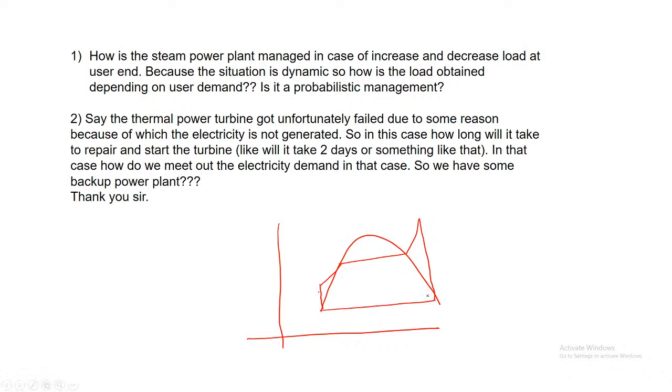This is our Rankine cycle in our TS diagram, and here we have 1, 2, 3 and then 4. Consider an ideal cycle with all efficiencies as 1. Now we are bleeding certain steam from here, which is 5. Since we are bleeding certain steam over here, we are taking X amount of steam. So till here it was 1, but after here it is 1 minus X, since X is a mass fraction which is taken out from the turbine.